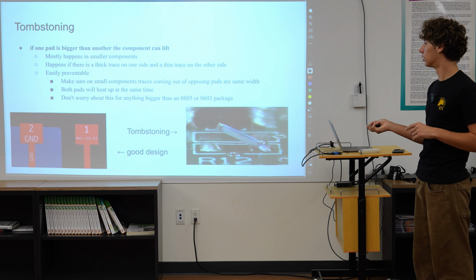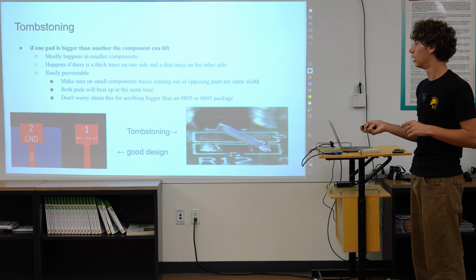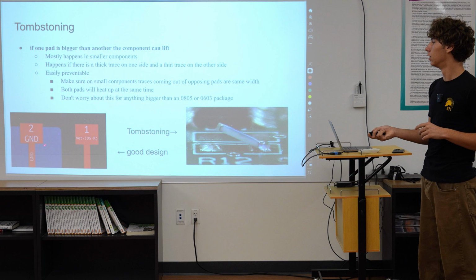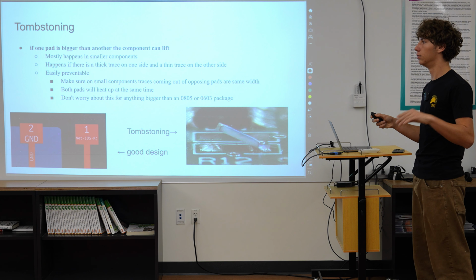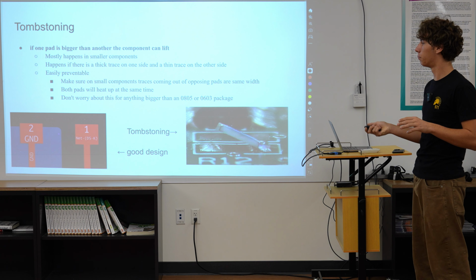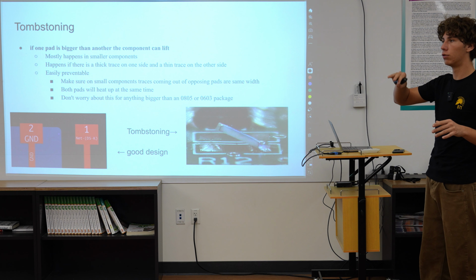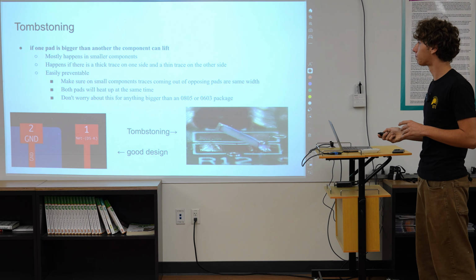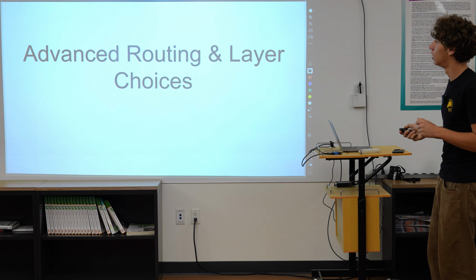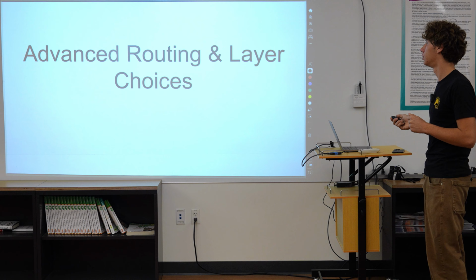So that's what tombstoning looks like, and this is what good design looks like. Because as you can see on both sides here, how hot they'll get compared to their surrounding environment will be the same for both pads, which means they'll both reflow at generally the same time, which means they won't have the opportunity to kind of tombstone up like that. Okay, so moving on to advanced routing and layer choices.